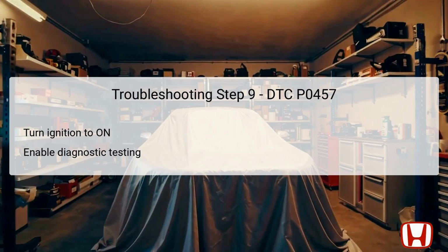With the ignition in the on position, technicians can now prepare to select diagnostic tests that will check the current state of the EVAP system. This step continues the process of narrowing down potential causes for the DTC P0457.